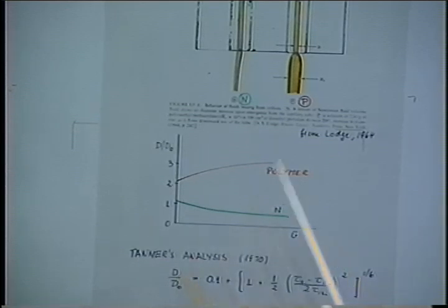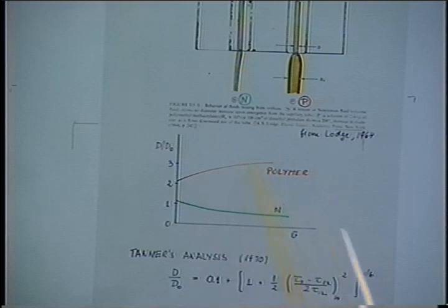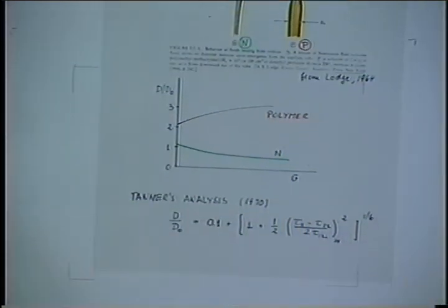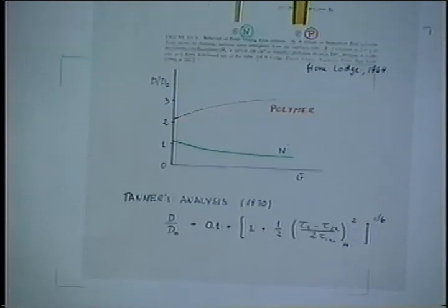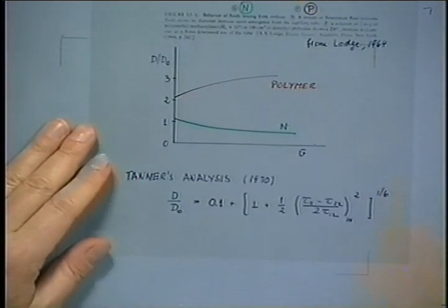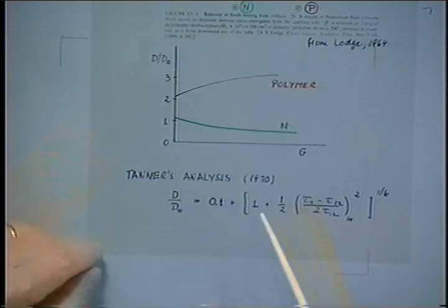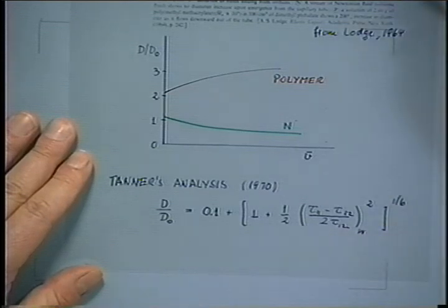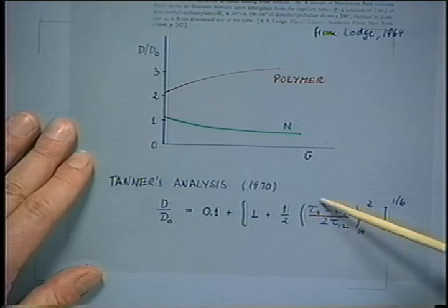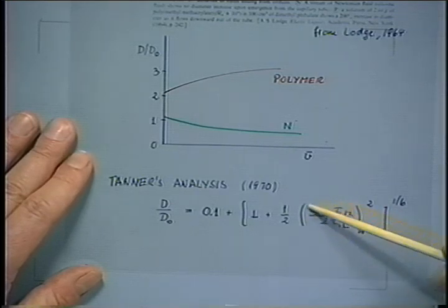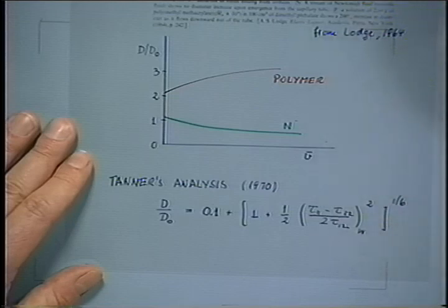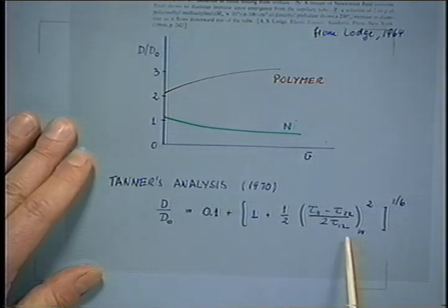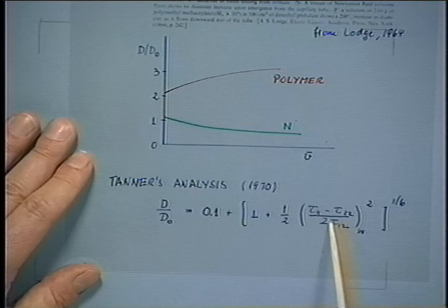He calculated the swelling, and he found, using a very simple model, it's amazing how nice it is in spite of all the simplifications. So in a very simple model, he found that the normal stresses in the shear flow here, this is tau 11, we have to talk about notation, but this is basically the tension along the lines in the material elements flowing downstream. And that's the shear stress.